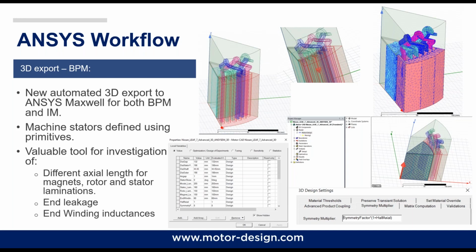The export gives a great flexibility to the user since it allows to change the parameterization of different elements such as coils, stator, and bands. Furthermore, it will also be possible to change and refine the mesh length for each object of the model.